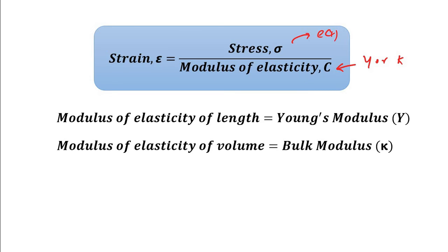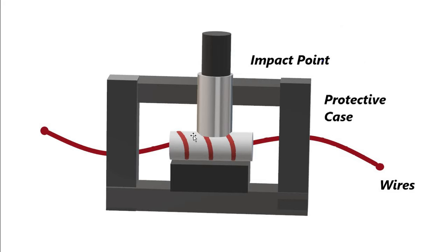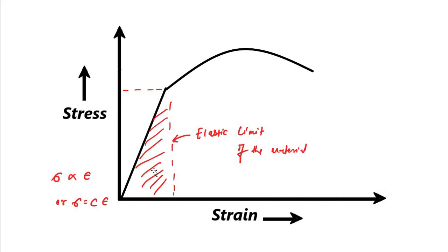Now everything else is the same, the design, construction, everything stays the same. The only thing that is important here is that the ferromagnetic material used in this magnetostrictive sensor should have a high proportionality or elastic range. That is the only requirement. Okay, so there some fine tuning adjustments are done.